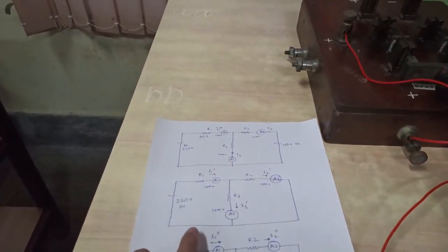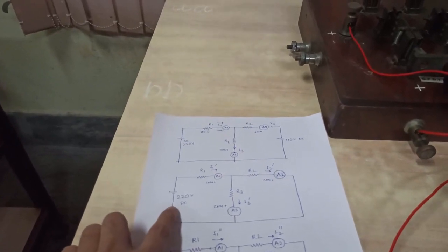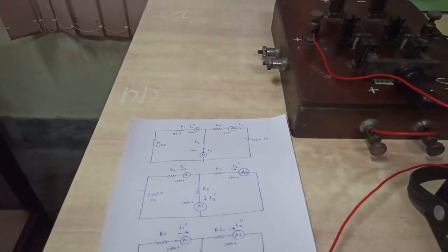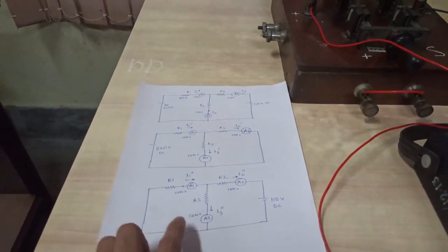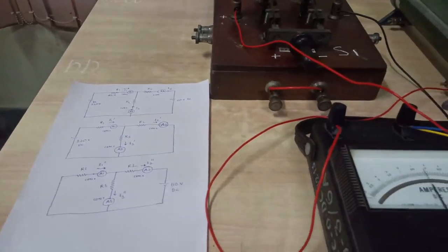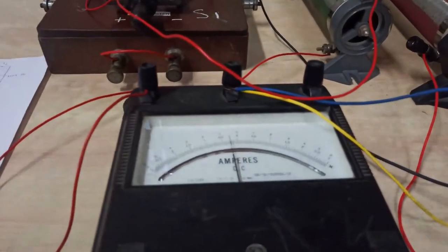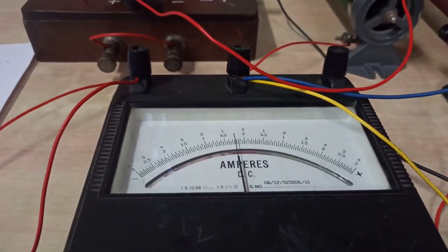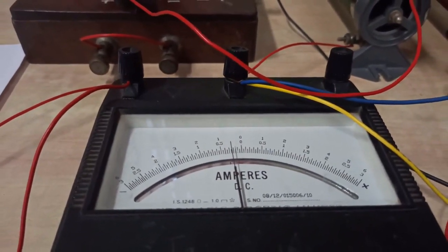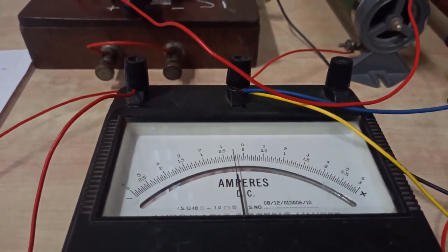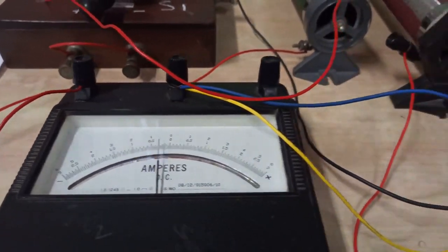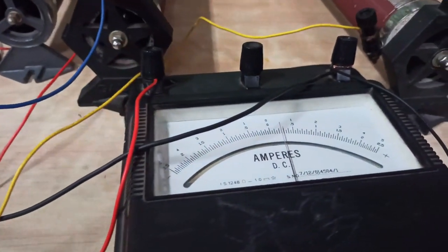And in step 2 what we had done, we had kept only 220 volt, and instead of 110 volt we had replaced that by a short circuit. So, now we are in step 3, and we are seeing current due to 110 volt source. Now if I look at this emitter 1, you will see that the current has gone negative. So, now I believe you have understood why we need an emitter which can give us both positive and negative direction of currents. We will note down this current, and we will note down the other current.